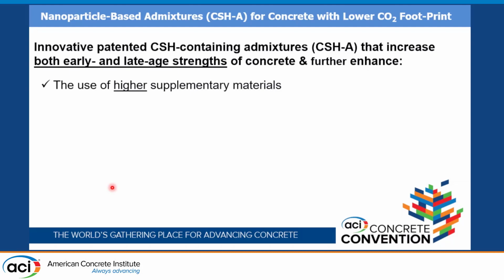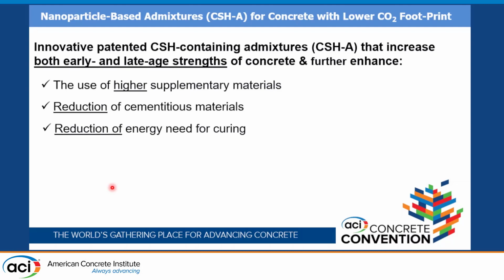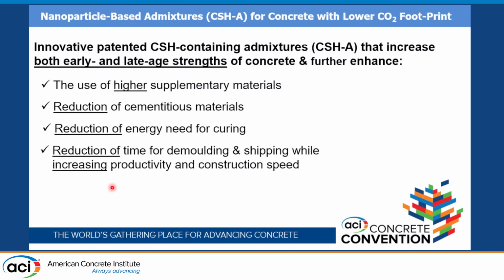And that increases both early and late strength for concrete and further enhances the use of higher supplementary materials, reduction of cementitious materials, reduction of energy need for curing, reduction of time for demolding and shipping, while increasing productivity and construction speed.